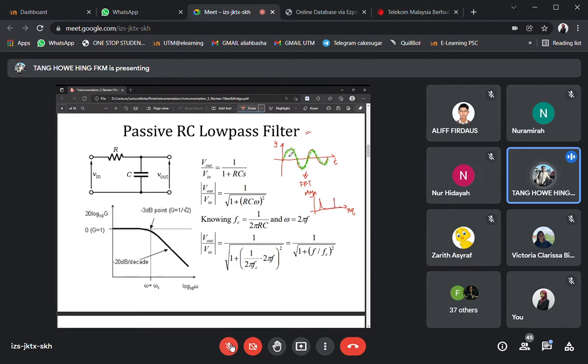Okay, so in this case, we are going to get two spikes. So you can see that in the time domain, the clean signal, which is the red line. So this red line is a sine wave, right? Let's say this sine wave is carrying a frequency of 1 kilohertz. Okay, so 1 kilohertz means that one complete cycle is equivalent to 1 millisecond.